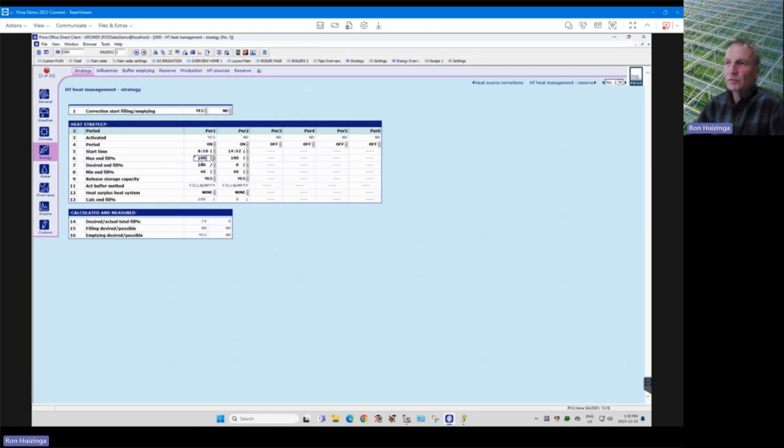Okay. Yeah. I was going to get to that a little bit later, but we can talk about it now since we're talking about filling the buffer. If you're driving your boiler mainly for CO2, then I would say you want to fill it up during the day. That's your main target. So you want to make this period your CO2 start time roughly, and you want to make this period your CO2 stop time. So let's say your CO2 stops at 4:30 in the afternoon, and this starts at 8:30 in the morning.